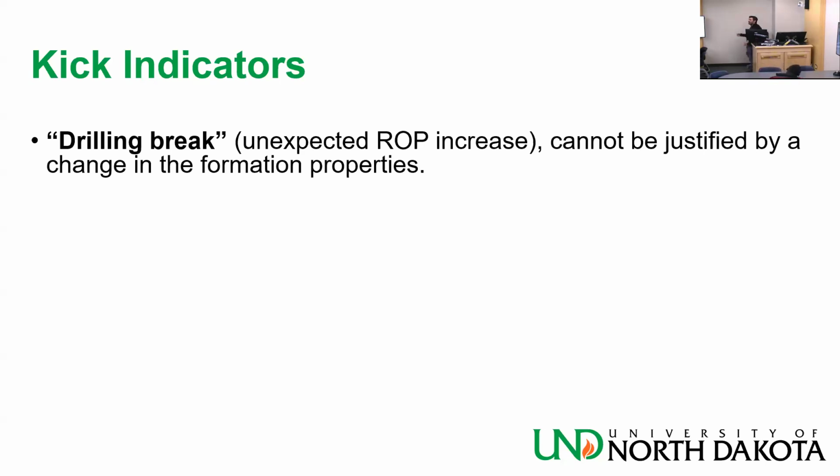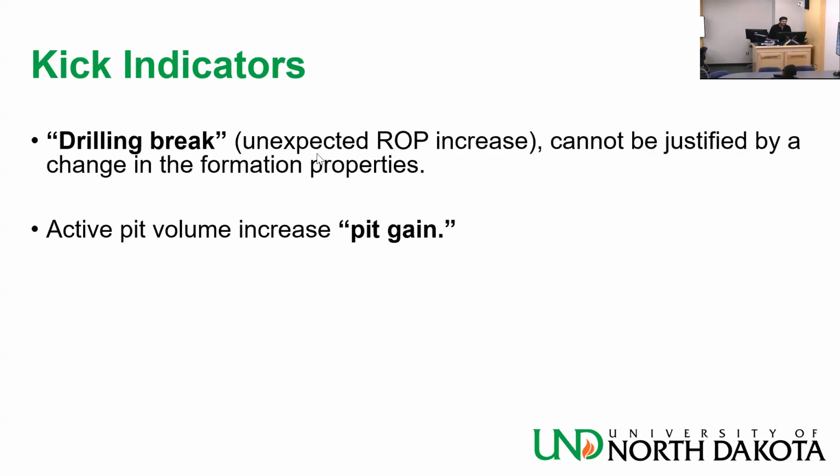If you drill and your ROP increases, it could be expected. But it could be because you're taking a kick, very important. We call it a drilling break. So that's one thing.